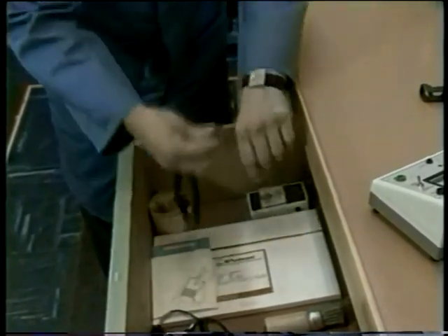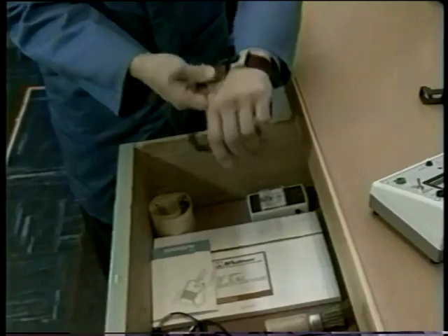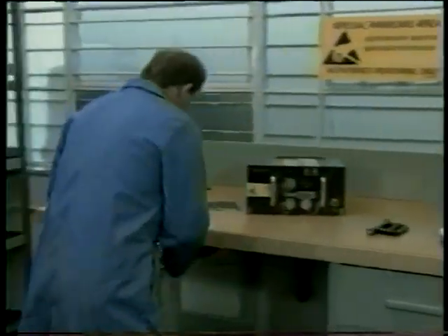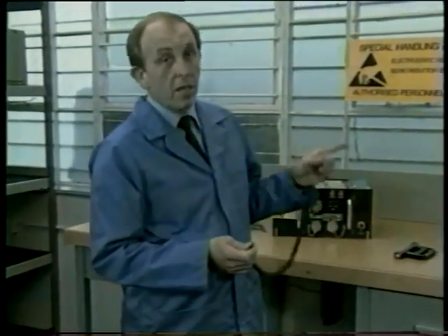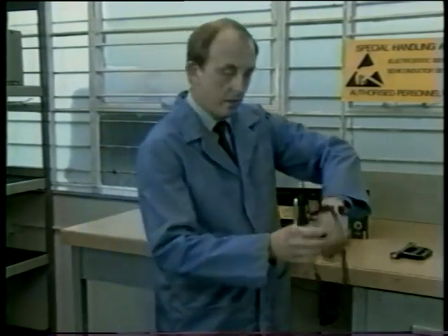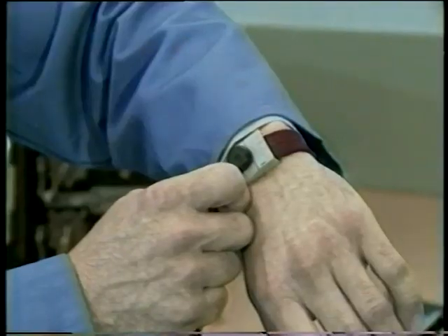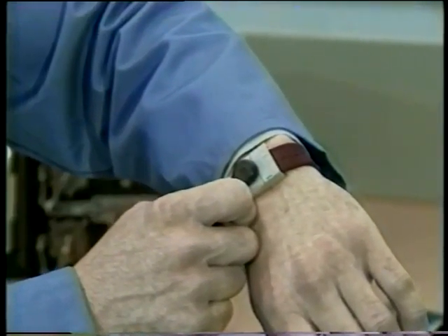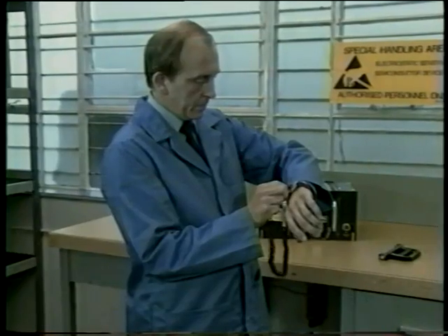The most important is the grounding of personnel via the wrist strap before even approaching any exposed and vulnerable circuits. That's fine, but I don't fancy being connected to ground when I'm using mains-powered test equipment. No problem. There's a 1 megohm safety resistor incorporated into the ground cord. Currents greater than a few milliamps are harmful, and the resistor will limit currents to well below this level.